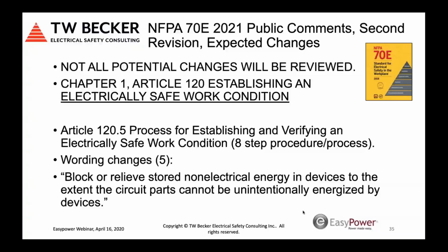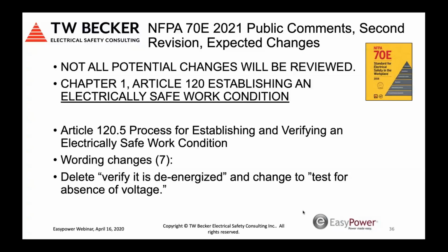So step 5, some wording changes to clarify, again, non-electrical energy. So mechanical energy, the wording is now changed to block or relieve stored non-electrical energy in devices to the extent the circuit parts cannot be unintentionally energized by devices. In item 7, verify if it's de-energized.